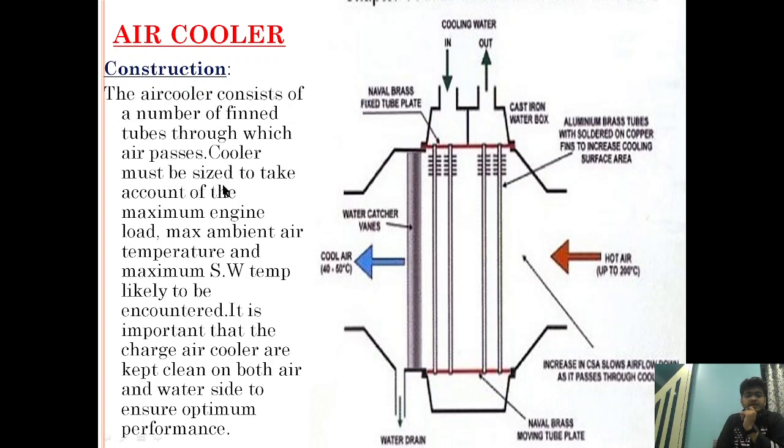The cooler must be sized to take account of the maximum engine load, maximum ambient temperature, and maximum seawater temperature likely to be encountered.